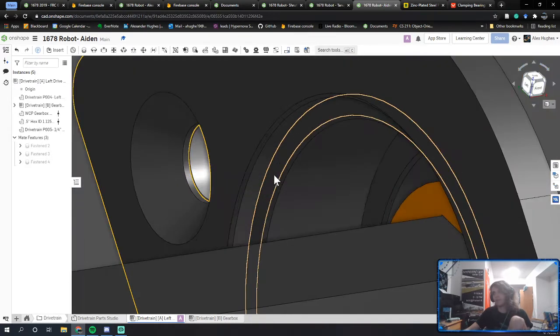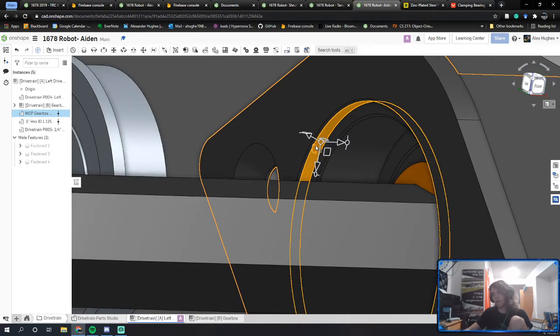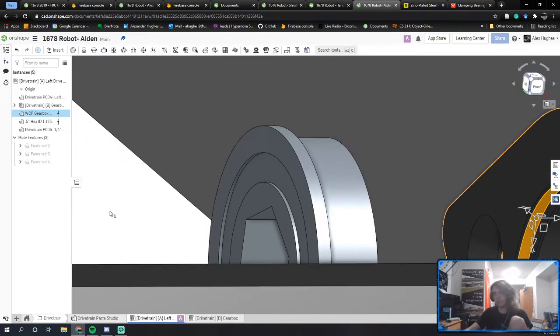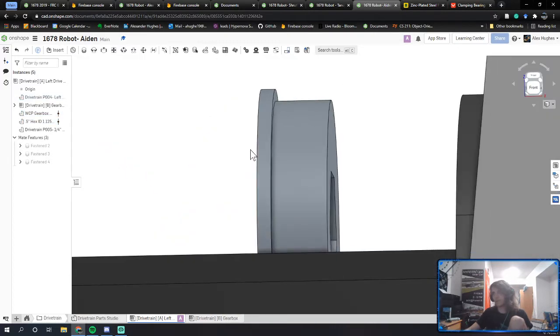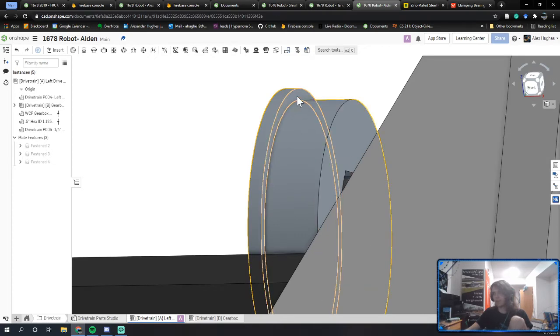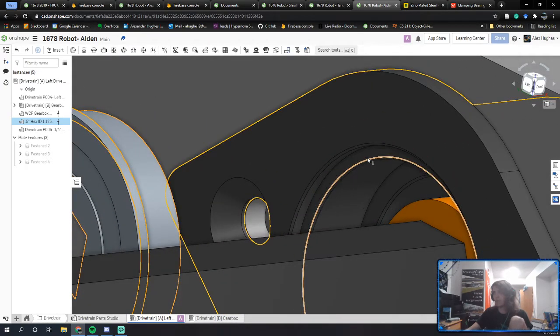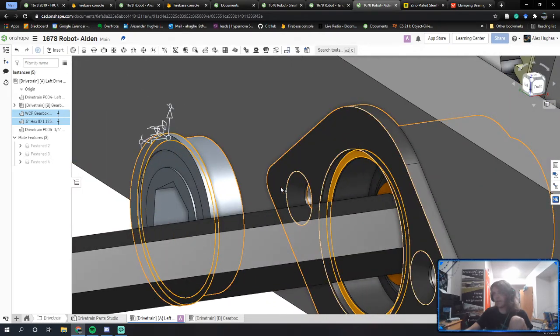So as you notice, there's an inner lip here on the bearing block, and you have this outer thing that has a diameter of 1.25 inch, which matches the diameter of this, almost. And then you have that inner lip, and so what you're doing is you are mating this surface, this flange of the hex bearing, to this inner lip right here. So the bearing can't go any further in.